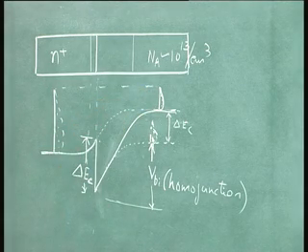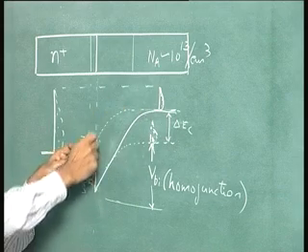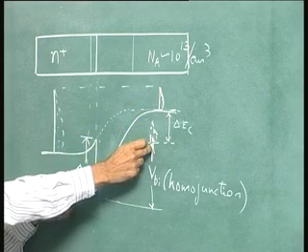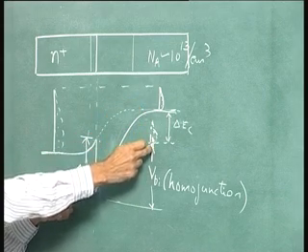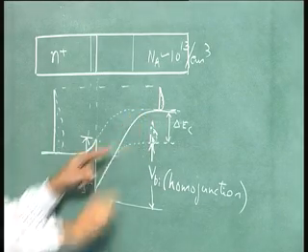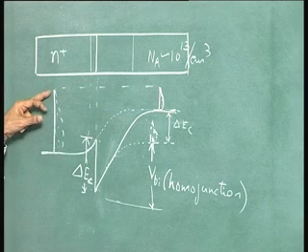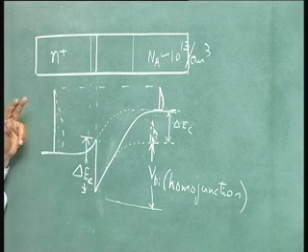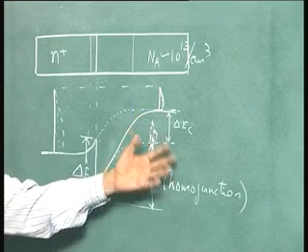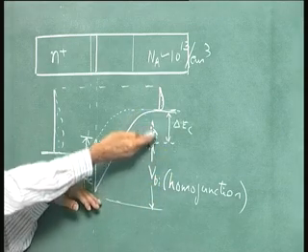I will repeat it. So, if the potential variation were same as without notch, this whole thing would have been shifted down here. That is what you get in a homojunction. But now, if that is the situation, the carrier distribution here, highest energy electrons are lower than the highest energy electrons there. As a result, the electron transfer will still continue beyond that point, beyond that VBI of homojunction. That means, the potential here will go up further.